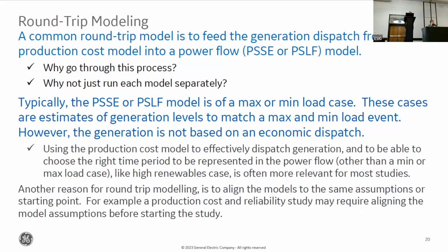Generally, the economic dispatch is going to incorporate the nuances of natural gas prices, other fuel prices, limitations on the grid, limitations on renewable resources, and then you feed that back into either PSSE or PSLF.